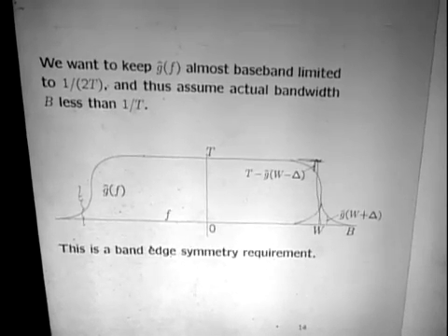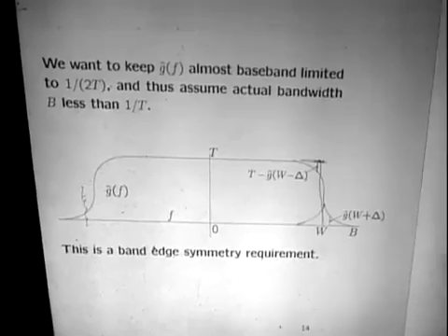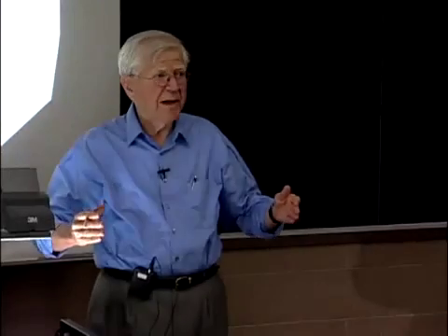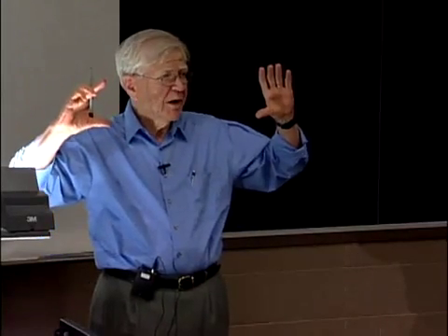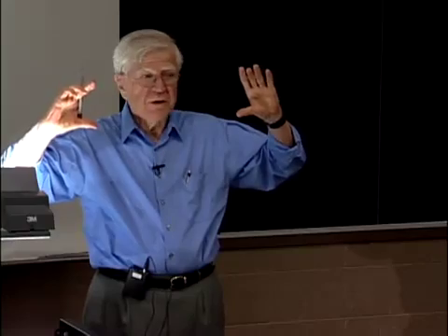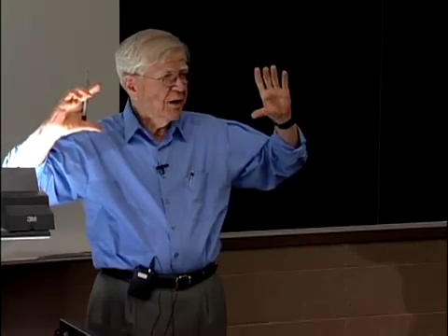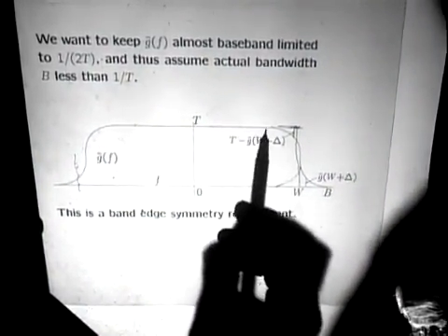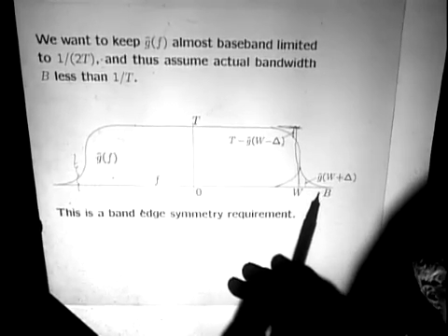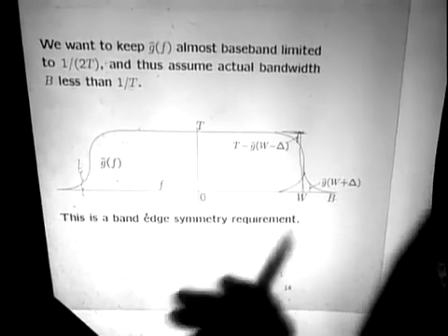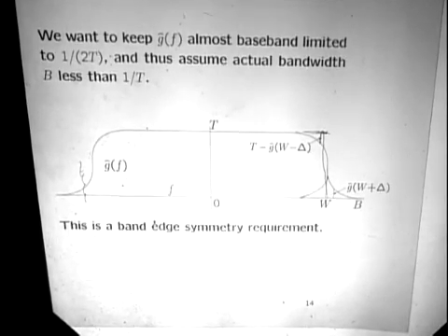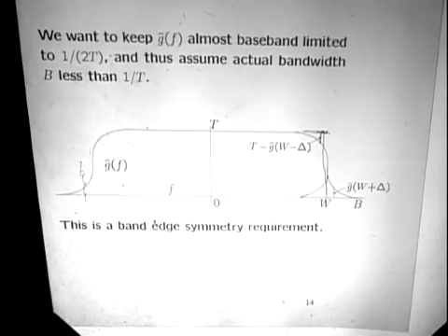So this makes the problem easy for us. It says we would like to have a rectangular function. That has too much delay because in particular the inverse Fourier transform of that, because we have a discontinuity, can drop off at most as 1 over t, which is pretty slow. We've gotten rid of the discontinuity. We've also gotten rid of the slope discontinuity, the way I drew the figure here. And therefore, we can wind up with a function which decays as 1 over t cubed, which is a whole lot better than 1 over t. Okay?